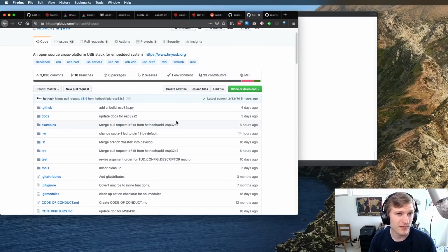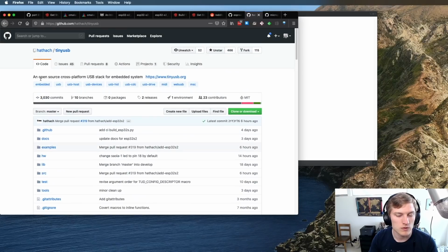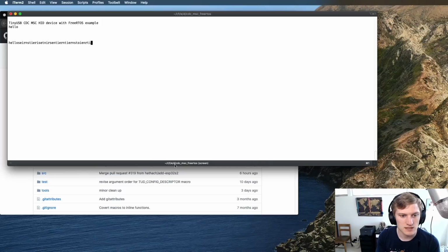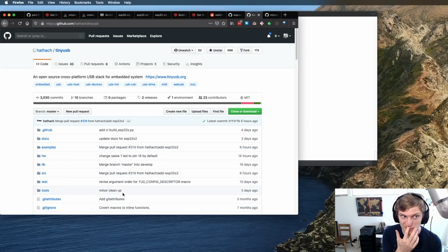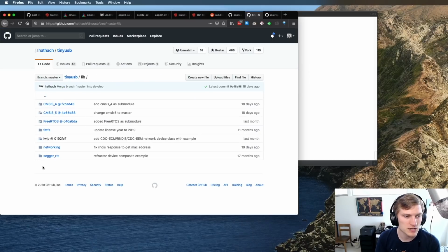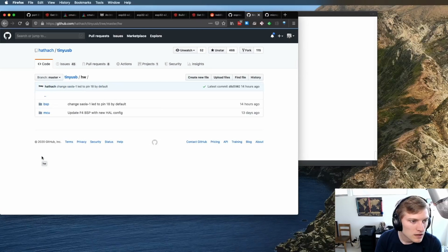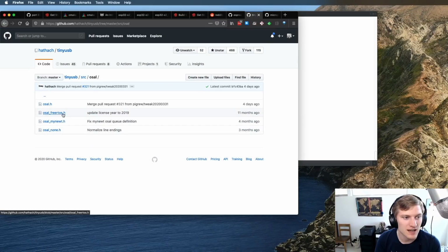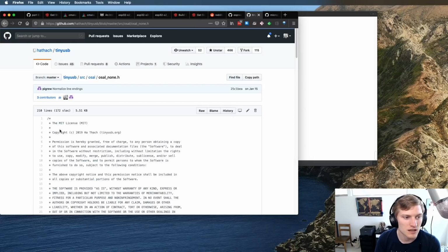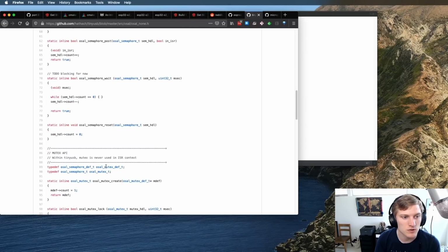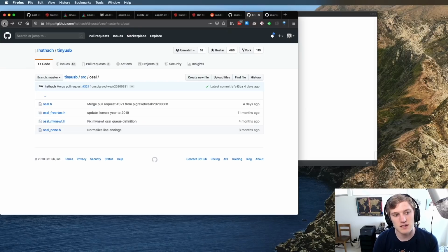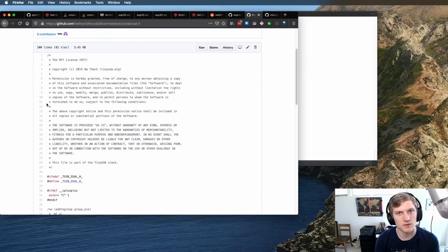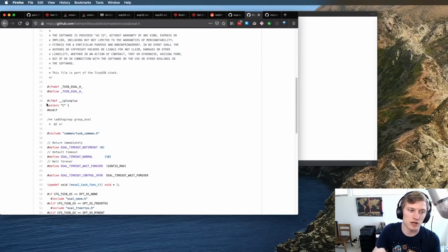I think my answer is that I'm going to follow the TinyUSB model. Tack has a lot of experience, and if you notice, the name of the example is actually CDC mass storage FreeRTOS version. So TinyUSB already has a notion of an OS abstraction layer, and I don't know where it lives. It's somewhere in here. OSAL. So he's got an OSAL, and you can see that it has FreeRTOS and a few other options in it, and then none. When we use TinyUSB right now, we just do the none version. But we're going to get to the point where we are using FreeRTOS. So I think what we'll probably do is inherit this OSAL from TinyUSB and use that as our way to minimally plug into an RTOS, such as the FreeRTOS that ESP32-IDF uses.